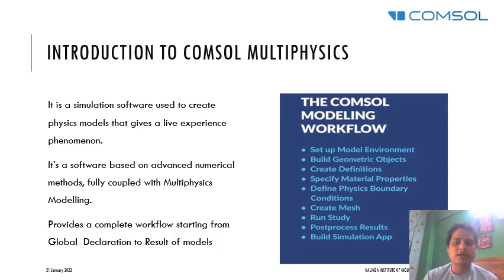Once the mesh is created, you need to see the mesh either in extra fine condition, finer condition, or normal condition. Then you have to go for the run study operation. In that, you need to select the operating frequency. You need to select the number of modes that need to travel inside the core. Then once you press the compute button, the simulation will run for half an hour to 1 hour or more, depending on the processing speed of your system.